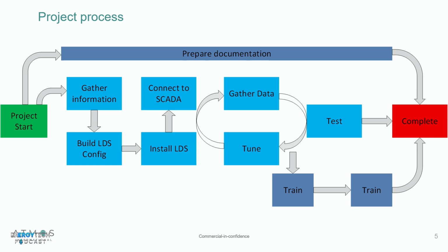So we do a lot of functional testing at the factory acceptance test. But then, if you see, I've got the testing after the tuning, right? We already have the real tuned system and the real data, so we can push leaks into that. And then we also do a bit of leak and performance testing.